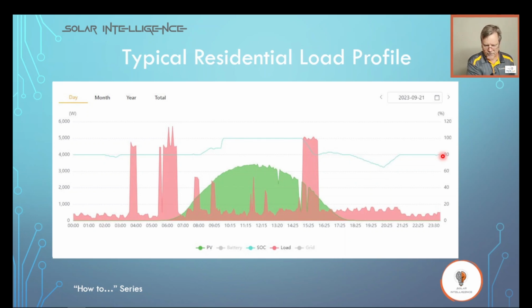All right, so what are we talking about? We're saying that we've got excess energy. This green is excess energy. Maybe that energy went into the battery, was used to charge the battery. So as we can see, the battery here was at 80%, and there's a little dip over there. We'll see just now why there's a dip. But as the sun comes up, you see the battery state of charge increases. So obviously this excess energy, this extra green, is used to recharge the battery.